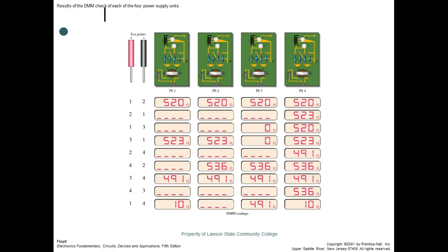And by the way, that's something you should get in a habit with. Just because you flip a breaker or do something does not mean that the circuit is wired the way it's supposed to be wired. So when you trip a breaker or pull a disconnect, you always check where you're working for power, for voltage, right? You understand that? That should be something you get used to doing right off the bat.